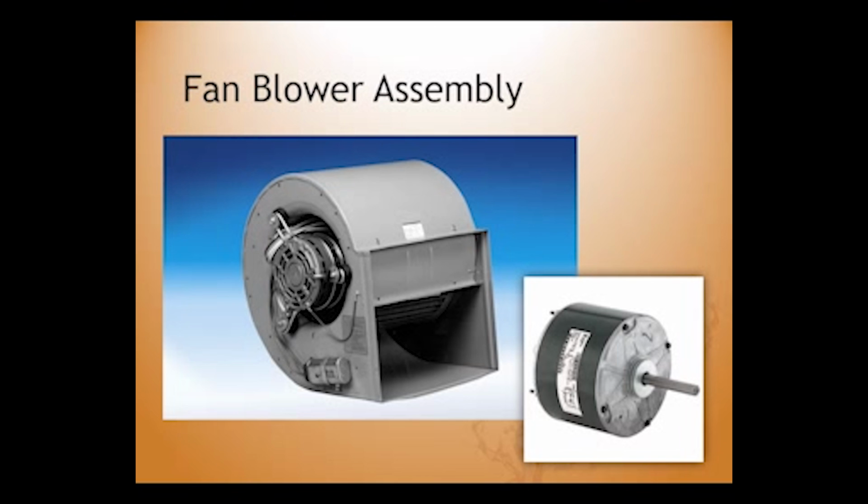This type of motor will have 3 different speeds. It will run on low speed continuously for circulation inside the area. It will run on medium speed for any heating modes, and it will run on high speed for any cooling modes with the air conditioner.